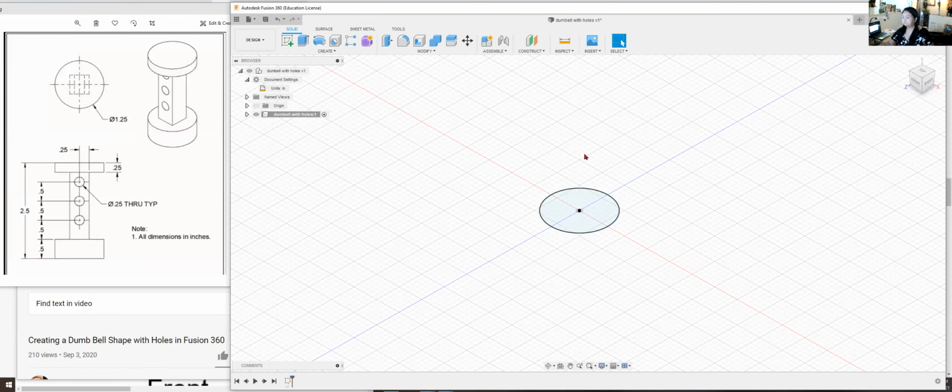We're going to extrude it, and we're going to go up. I'm looking here on the sketch. We're going to go up. It says here 0.5. That's going to be the height. So I'm going to left click and highlight the whole circle, kind of like a darker transparent.